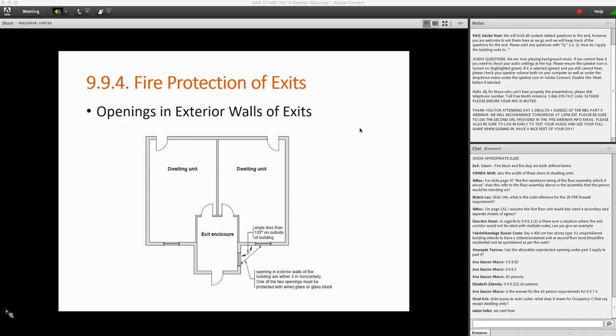Yeah, so I'll go over that again. That requirement under 9947 for stairways in 2-story group D or E buildings, so that 25-meter travel distance is measured from any point in the suite to an exterior exit. So you would have to measure down the open stairs as well to the exterior exit door on the ground floor level.